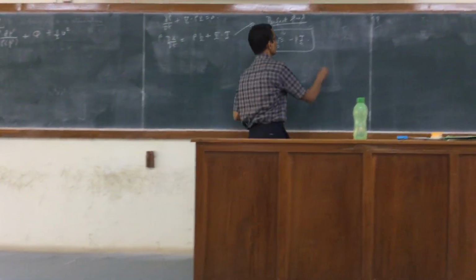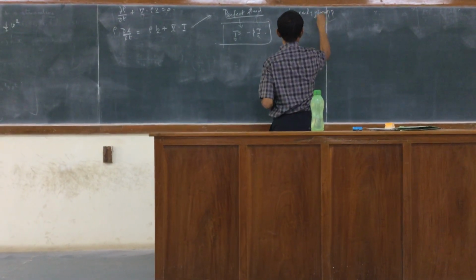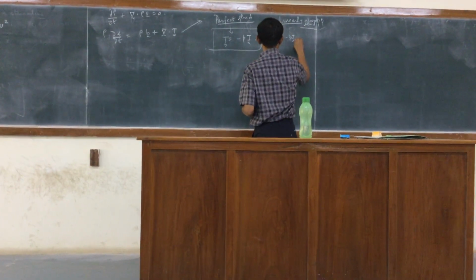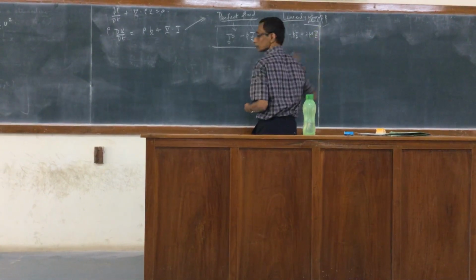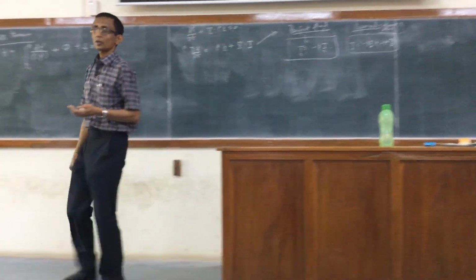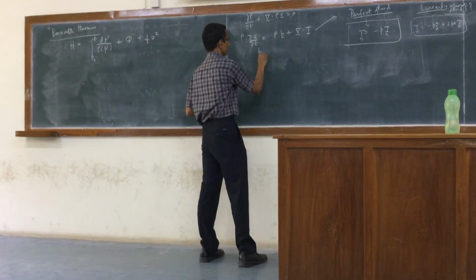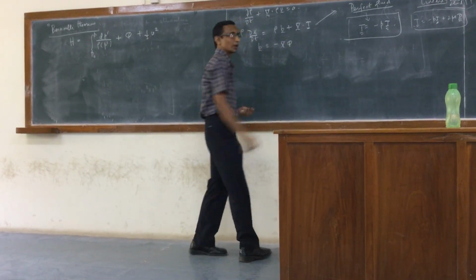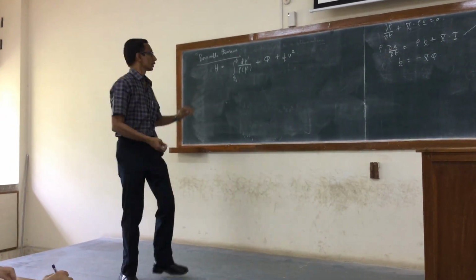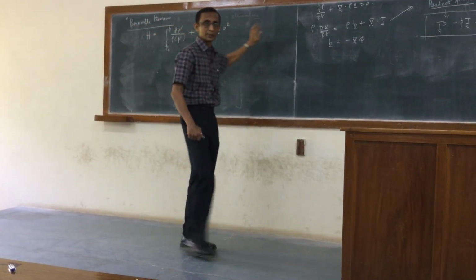So the linearly viscous fluid and the perfect fluid are the two types of fluid we are now considering for the Bernoulli theorem. This is the perfect fluid. Now for the perfect fluid, we further assume that the body force can be written as the gradient of a potential. So we consider a conservative force throughout all of the statement of the Bernoulli theorem. That is where the phi comes in, the phi that appears in the Bernoulli theorem.